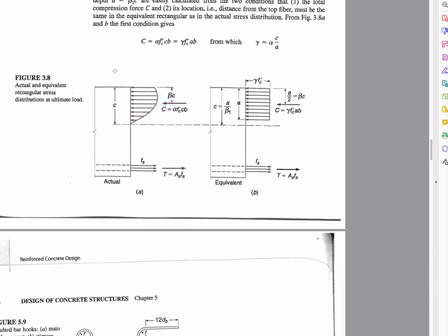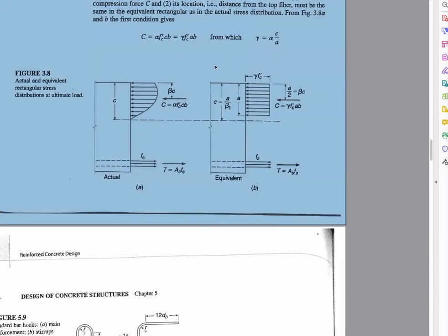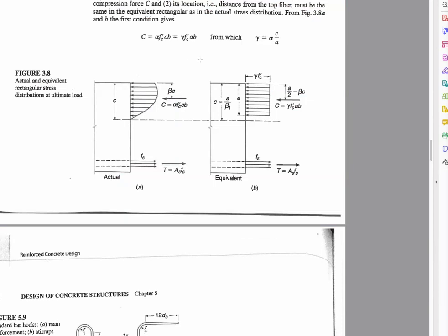This, similar to that oddball pyramid shape in shear, is difficult to handle mathematically for solution in simultaneous equations and so on, and trying to sort out what's the thickness of a section needed or how much steel is needed would be the question at hand here. And we will need to mimic that somehow, and something called a Whitney stress block was developed that looks like this.